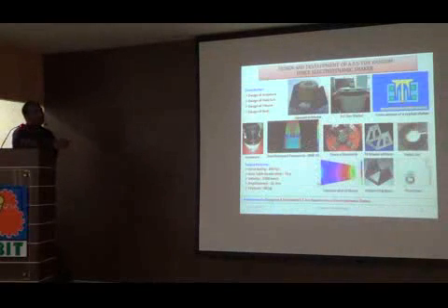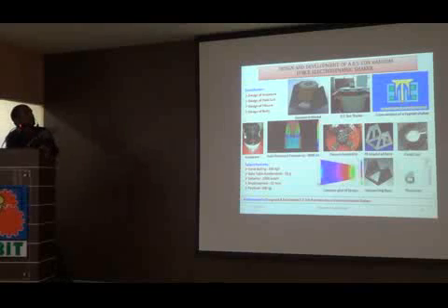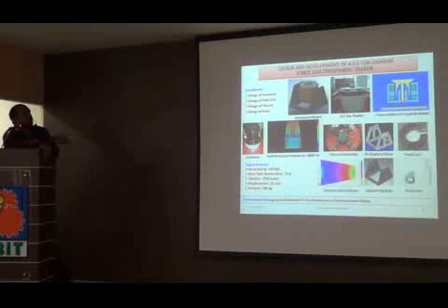Right. We will show you some of the case studies we have done in vibration science. As a part of indigenous development, we have developed some kinds of shakers. As I have mentioned before, shakers are of two types. We call them electrodynamic shakers, and they are either air cooled or water cooled. In air cooled, the heat that is produced inside due to the field coils is cooled by air. If water is used for cooling, then it is called water cooled.